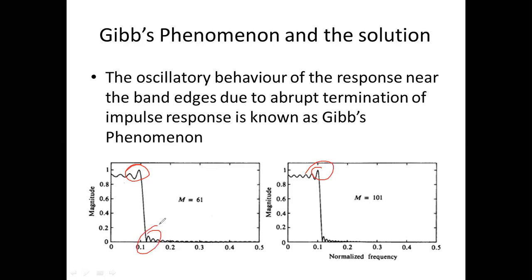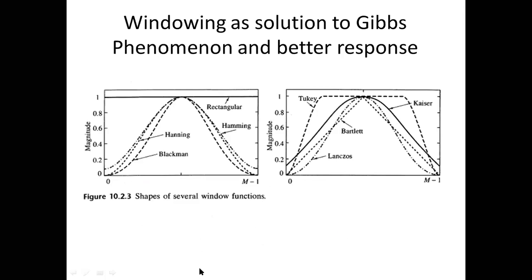the transition band. Okay, so windowing, other than the rectangular thing, picking the finite values is not ideal. So you should rather have something which is tapering in nature. Let me show you how it works. A typical rectangular window's impulse response will have ones throughout the entire function, from 0 to say order 21 or 31, whatever. The entire duration you will have all ones.